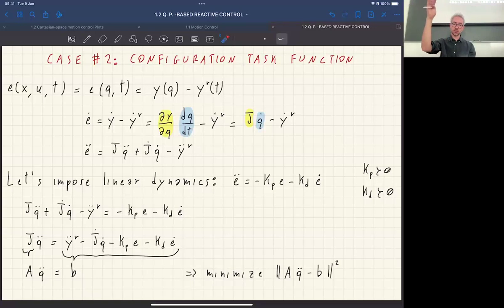So we saw the case of a position task, of a velocity task. What we are missing is a case where your task depends on the control inputs. That's very often the case where you want to just minimize the control inputs, and it's typically a secondary task. It's not your main objective.